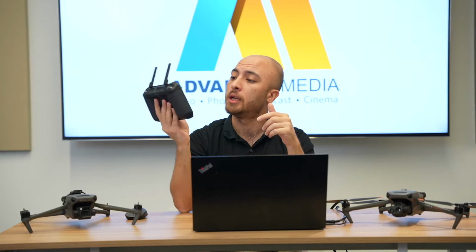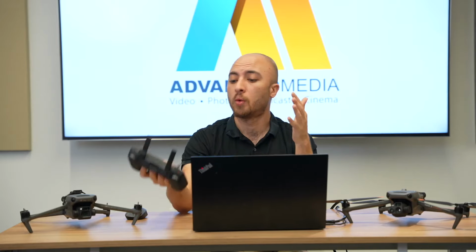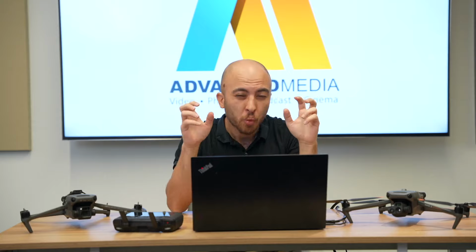And we now have something called advanced RTH. What is RTH? It's return to home. So imagine a scenario where the drone is away and you don't want to fly it manually to your take-off point, or the home point. There is a physical button here called Return to Home. Once you click it, the traditional way was that the drone would climb to a preset altitude that you put in the settings, like 30 meters, and fly straight to your home point.